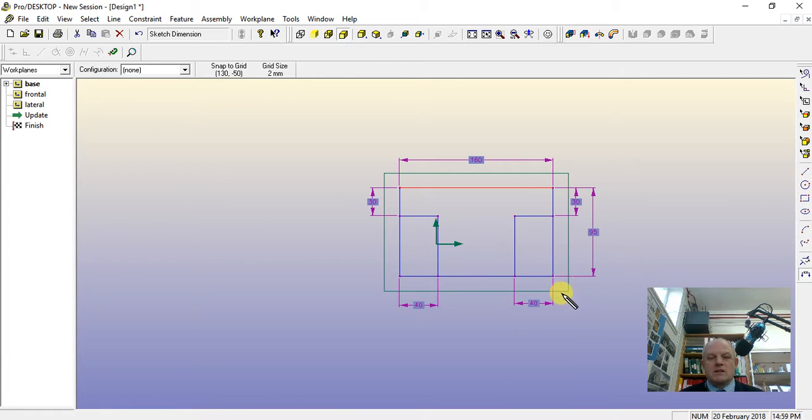Prodesktop won't like cutting this out. There's too many lines. So I'm going to have to use the seatbelt looking one here, and I have to click on that once, twice. I have to do it twice because in the computer's mind there are 2 lines. Once, twice, once, twice, once, twice. Now that's the t-shirt shape. I'm not worried about the dimension lines, they're just there to help me create the shape.